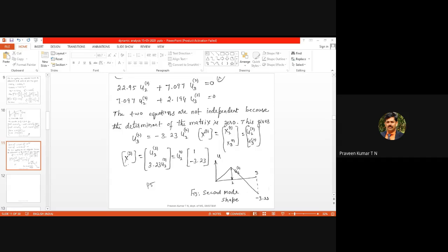From lambda we can get the first natural frequency f1 and second natural frequency f2. Corresponding to f1 and f2, or lambda 1 and lambda 2, you have to find out the modal shape m1. Those modal shapes, shown in the last two diagrams, represent how the bar nodes 1 and 2 are displaced.